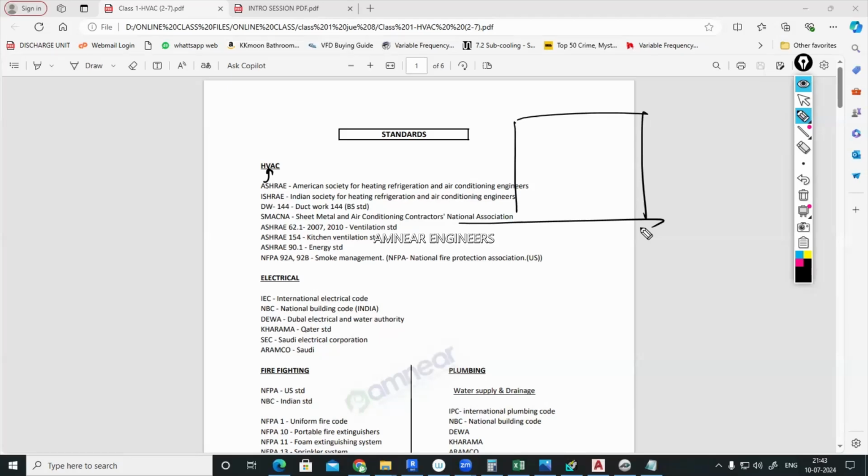But for commercial spaces like offices or classrooms, and especially a meeting room, the number of people within that space will be high. Since that space is tightly sealed, it is not possible to achieve a 100% vacuum, but even though it is tightly sealed, very little atmospheric air is entering inside. So people will be continuously inhaling the oxygen, and they will be exhaling carbon dioxide. Eventually, the carbon dioxide concentration within the space will increase, and the oxygen concentration will decrease.